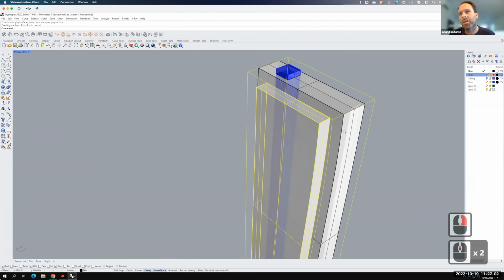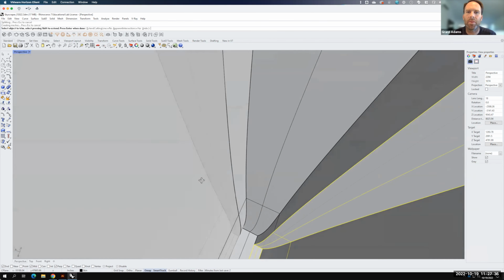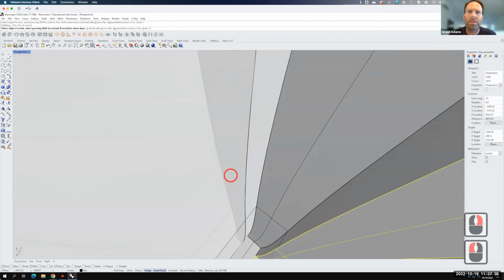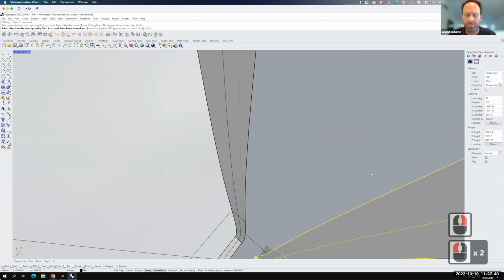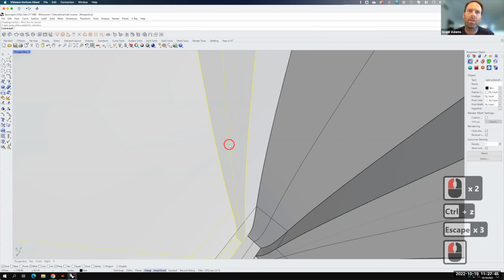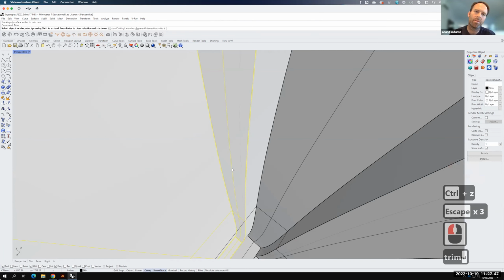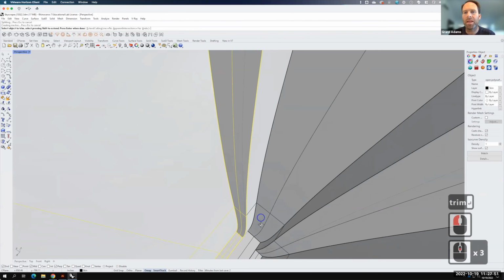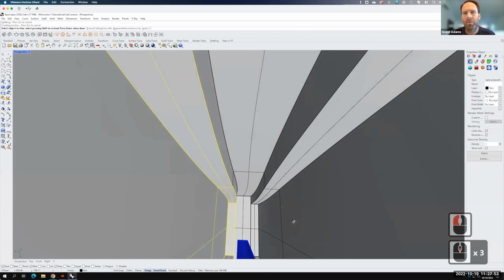Right? If I'm inside my building, there you go. You can see that it's actually been cut out so that it's hollow inside. There, you can see it down a little bit more. I'm going to do the same thing with this side. I'm going to take this, oops, sorry, I still had trim active. I'll type trim and I'll get rid of that part as well. So essentially I've made this hollow inside, except for my building core.